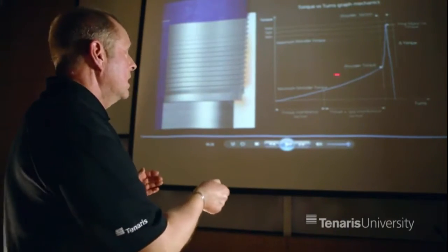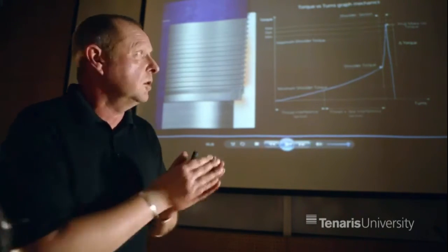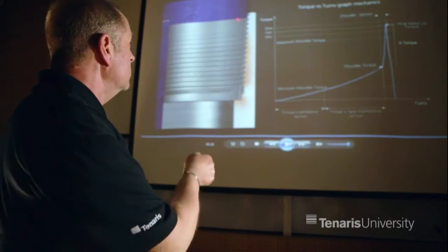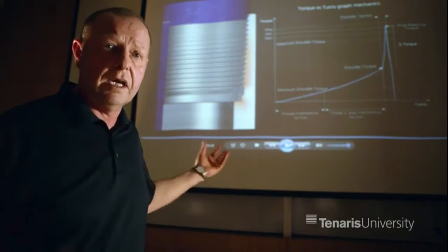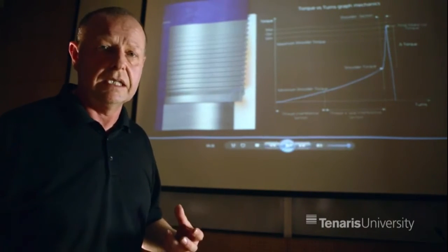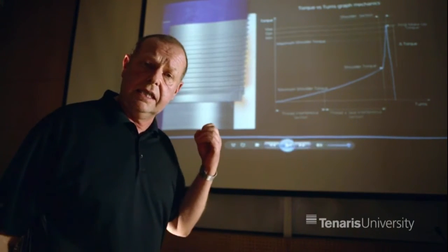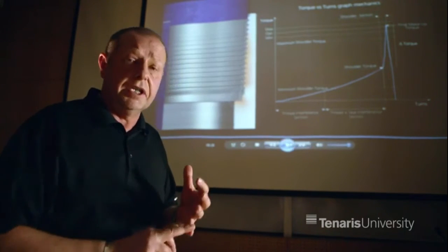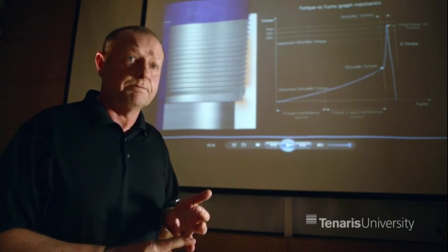Now, if it's not a specialist analysing this, inexperienced people looking at this won't know how to interpret it. Why? Because they don't know the design of this connection. So they don't know at any given time where that connection is in its makeup process. If the wrong graph is accepted and run in the hole, that actually means either a damaged connection or an incorrectly made up connection is being run in the well.